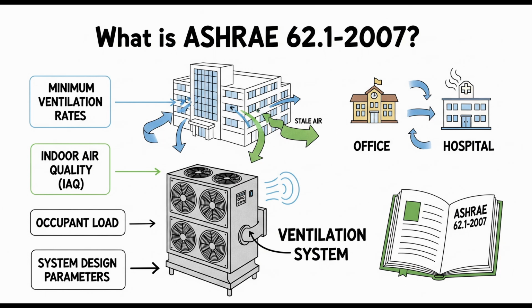Exactly. And it also says if your initial investigation found that the outdoor air itself is pretty bad, like high PM10 particulate levels, then you're specifically required to use MERV 6 or higher filters on that outdoor air intake too. Makes perfect sense. And speaking of wet parts, Section 5.10 gets into humidity control.